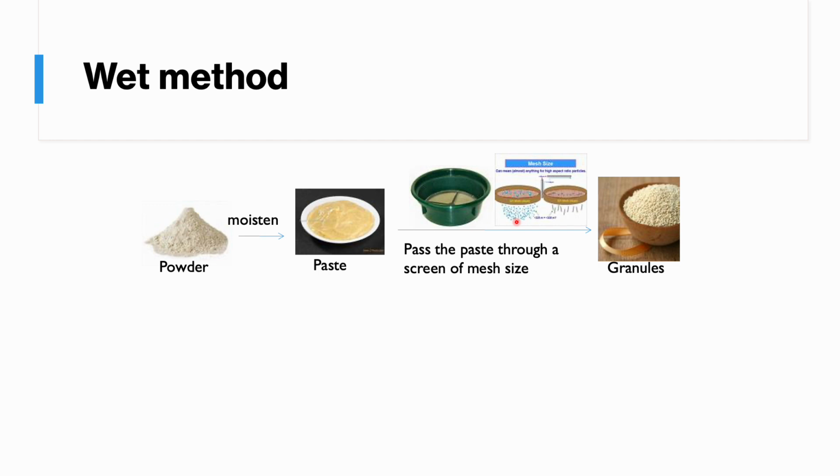It can be from 4 to 12 size range. Finally, this will make granules, and the granules will be dried to form dry granules. These granules can be medicated granules mixed into solvent or liquid for use, or the granules can continue to be compressed to make tablets.